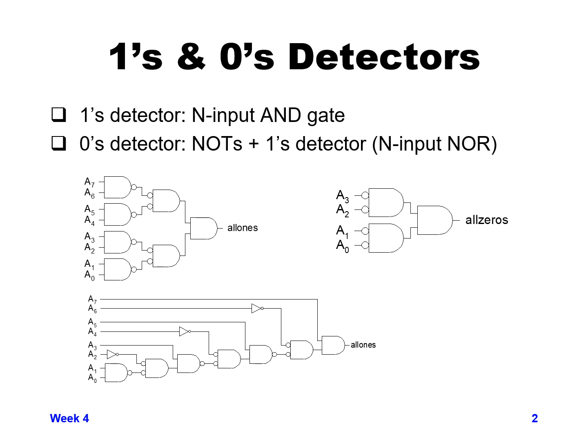You can do a similar thing for the zeros detector. You do a not function at the beginning and then follow it with a ones detector. So that could be a not and, which is basically a NOR, followed by a NAND. If you had an 8-bit input there, you would have 4 NOR gates followed by 2 NAND gates followed by 1 final NOR gate to give us a zeros detector. So this is just one way to implement it, probably one of the most common ways.